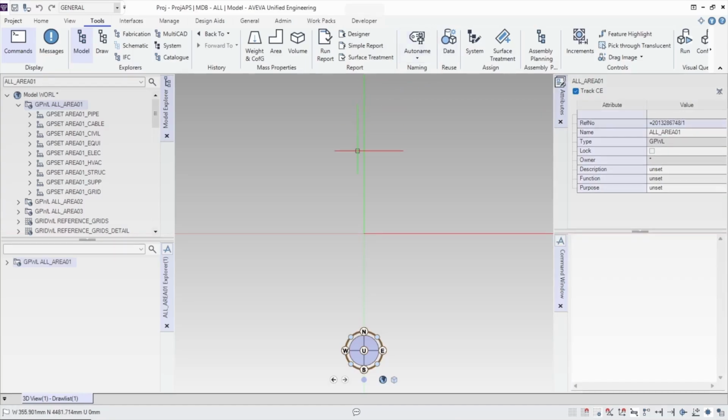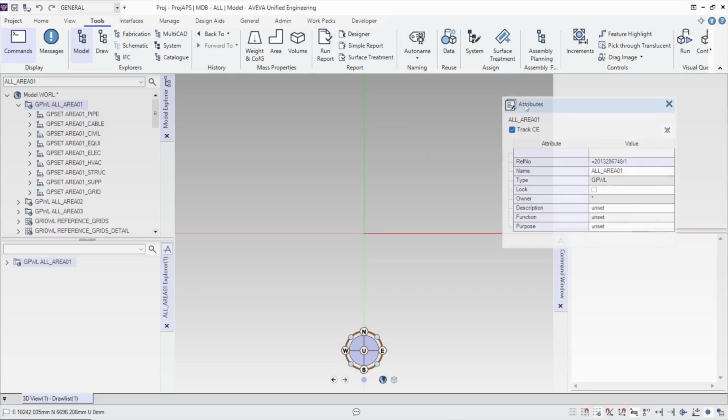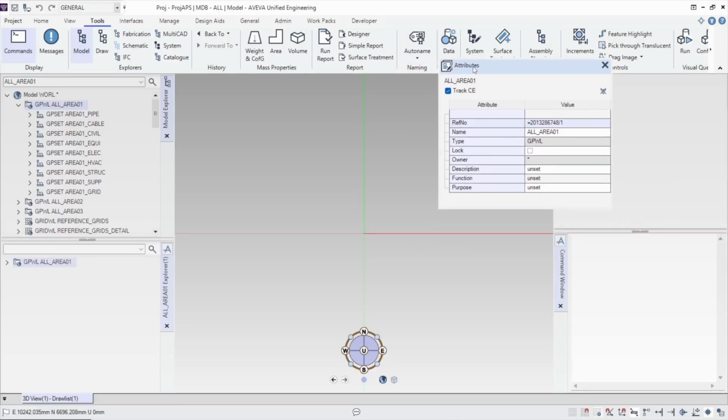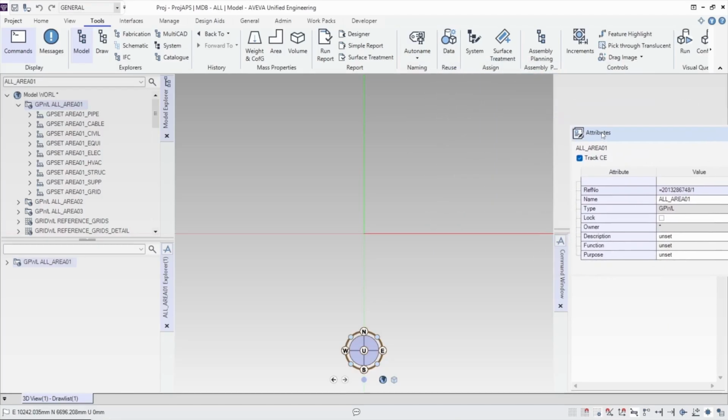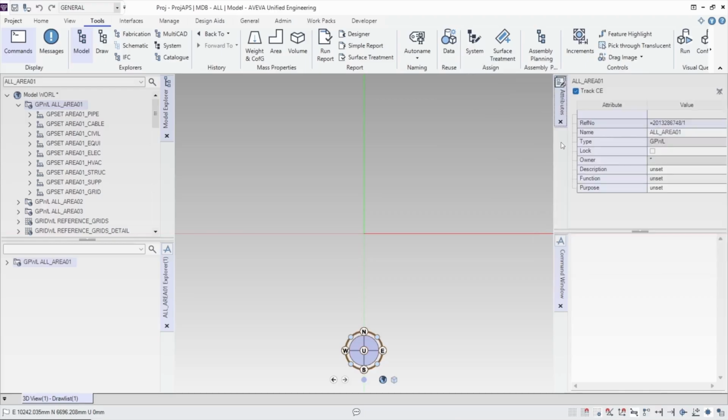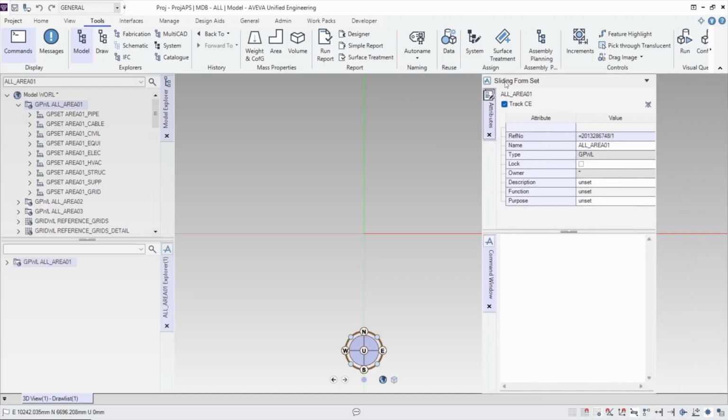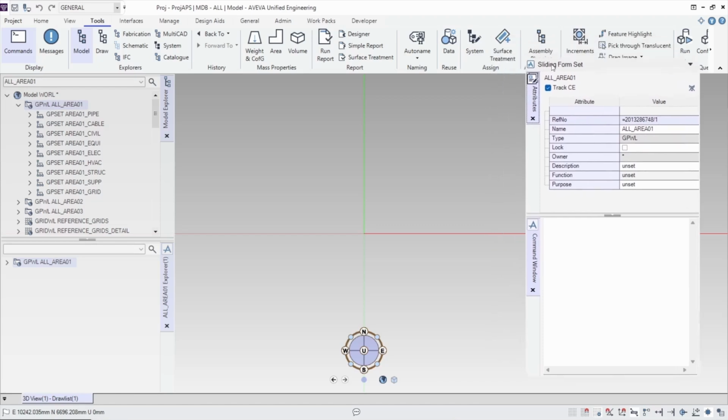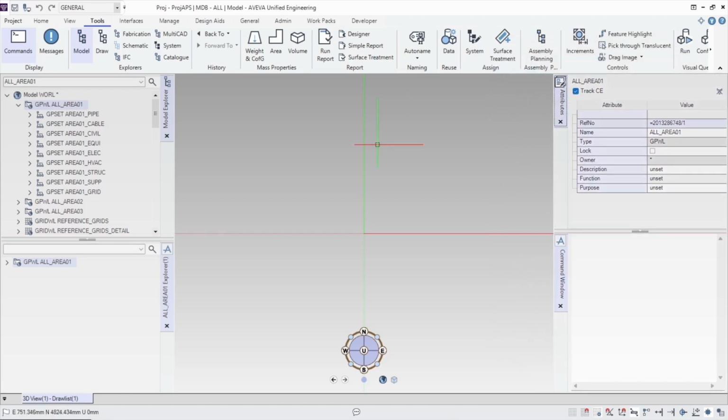For multi-monitor setups, forms are not restricted to the main application window. They can be undocked and floated onto a second screen, keeping the 3D workspace clear on the primary monitor. You can also float the entire form area, which can have multiple forms within it. Finally, right-clicking inside the viewing area opens the power wheel. This context-sensitive menu changes depending on the element selected, and provides quick access to navigation and editing tools directly within the model space. Next, let's look at the toolbars and disciplines.